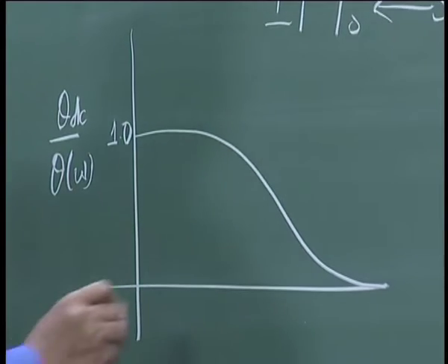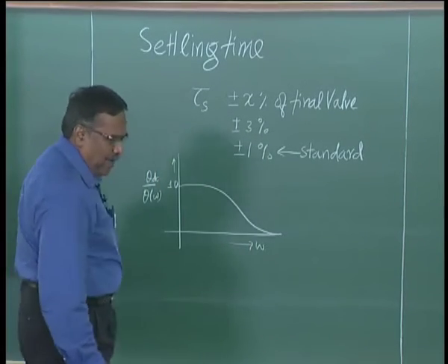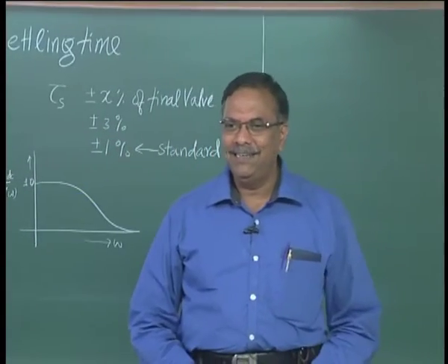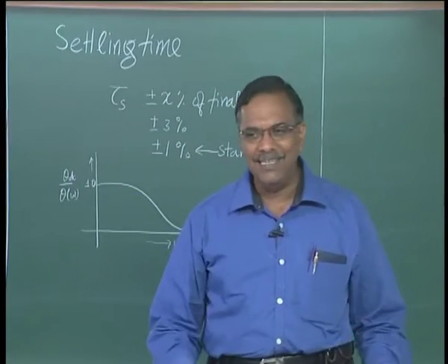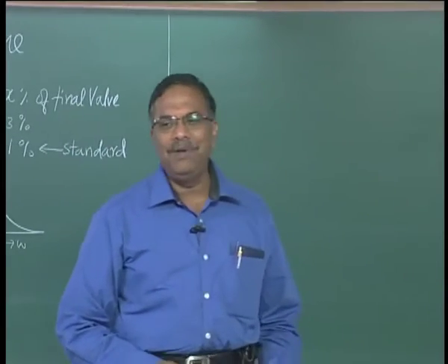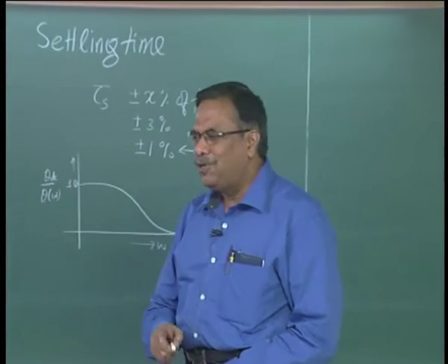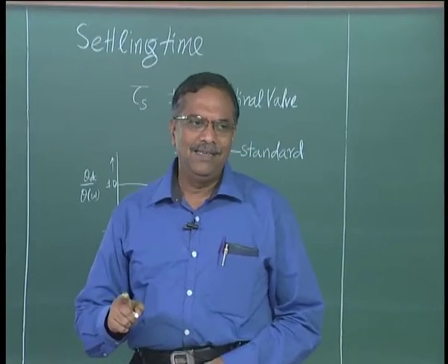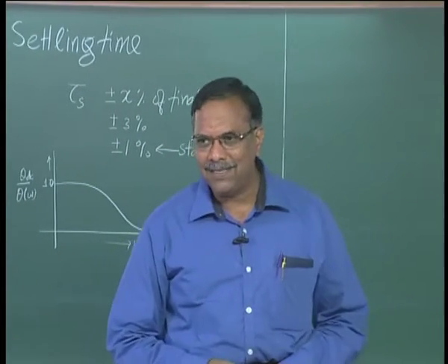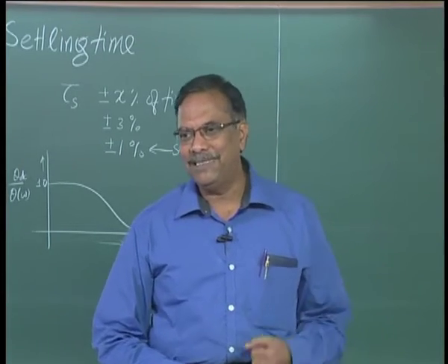if I vary the frequency given, obviously it does not make sense for a PMMC meter, right, because for the PMMC meter we have already decided it is no good for AC, because whenever current becomes negative, the deflection goes in the other direction, and either we have to put a center zero pointer. Normally we do not do that, very rarely we have a center zero meter for specific reasons, but most of the PMMC meters will start with 0 and anything negative we cannot measure, right.